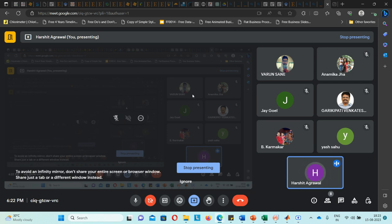There is one clause in IS 456. If the depth of the beam is not given, then it is assumed as 1/12 to 1/15 of the span. You know the span, it is 6 meter. So 1/12 of 6 meter or 1/15 of 6 meter. Between this, you need to assume the depth of the beam. I will tell you shortly.